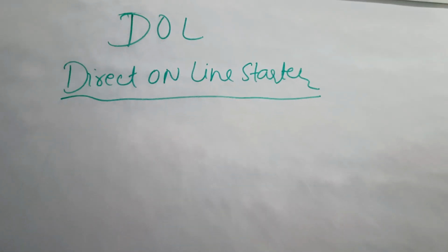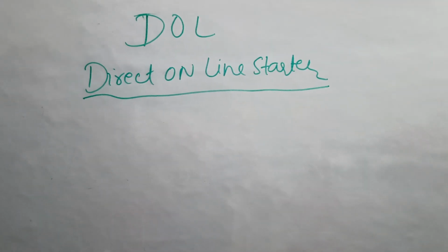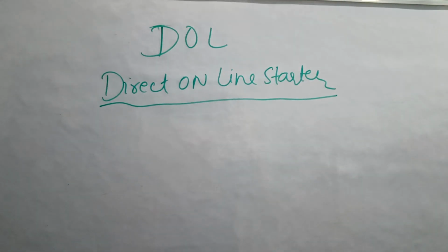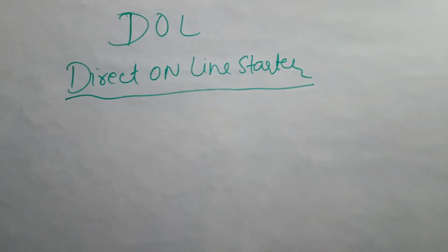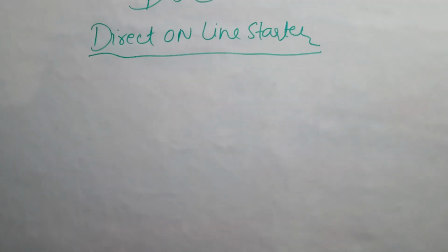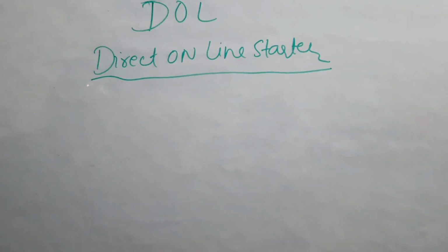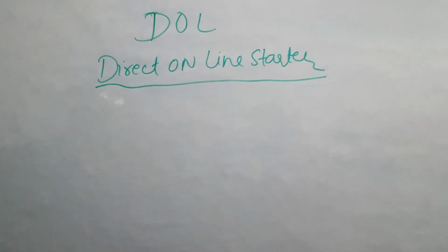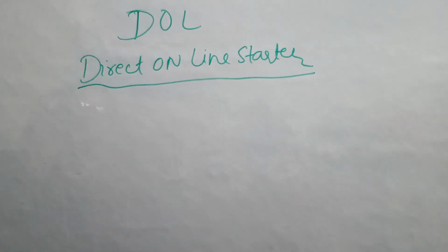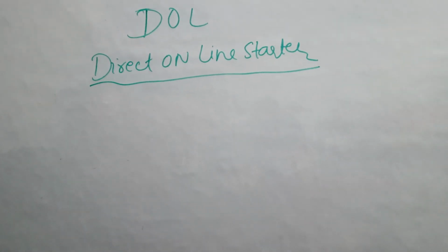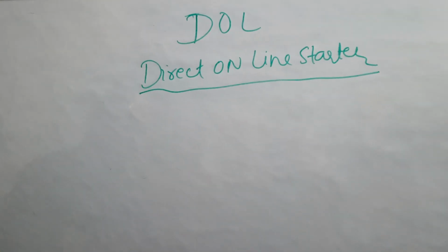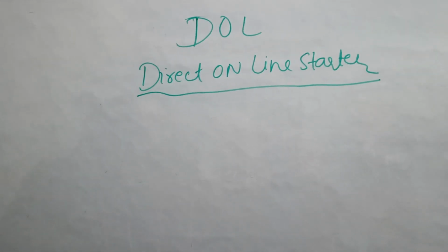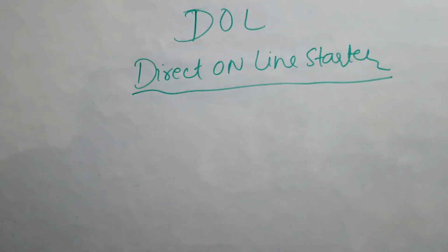I am a graduate electrical engineer, BE certified energy auditor and certified chartered engineer from Institution of Engineers India. Today I will tell you about the DOL starter, how it works and what the use of a DOL starter is. We can call it direct online starter because the power is directly connected from the power supply to the motor. There is no reduction of current or voltage. It directly connects the power to the motor.